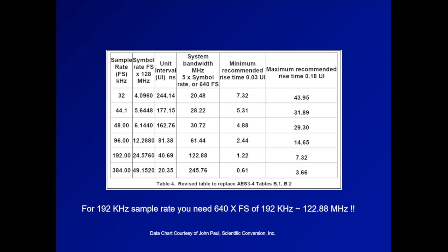So there are some things that you need to consider when doing this. We're finally in the radio business. We're dealing with higher sample rates than 48 kilohertz. Previously we were kind of used to 32, 44, and 48. And now all of a sudden we're jumping up to 192 kilohertz. And I'm here to tell you that it doesn't work the same way as those slower clock speeds. And you can have some inherent problems built in if you're not careful about how you manage this. And that's what this is about here. So next slide.